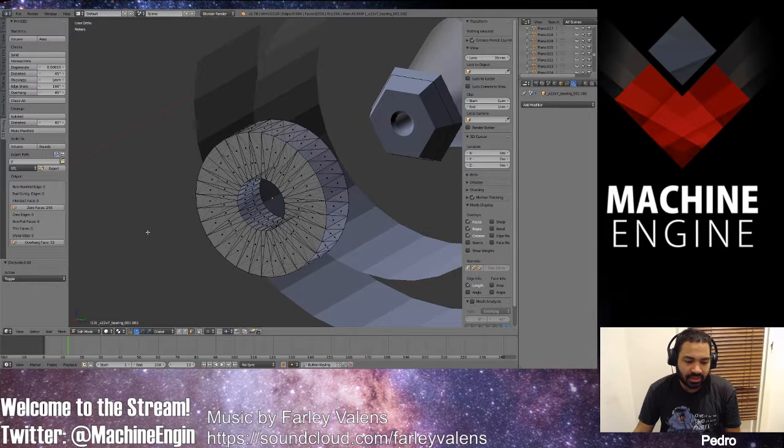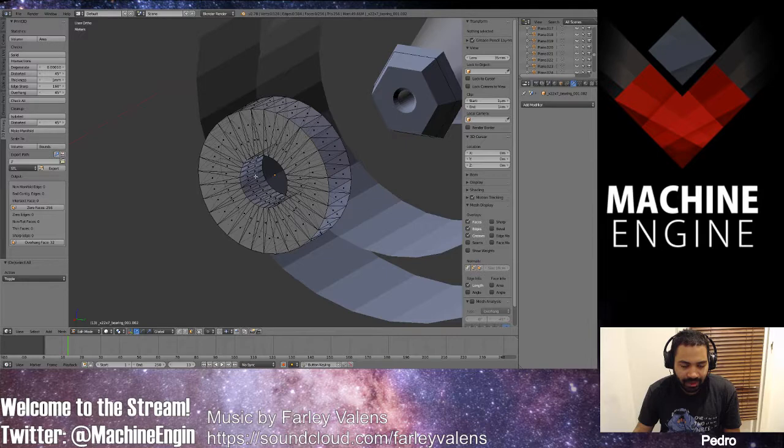that's why there are a lot of popular programs out there to do some kind of post production on 3D models, like Mesh Mixer. Mesh Mixer works if you get a random 3D model from somebody and you have to print it. Then you can load it into Mesh Mixer, because it can load all kinds of models, and then you can fix the model so that it comes out on a printer.